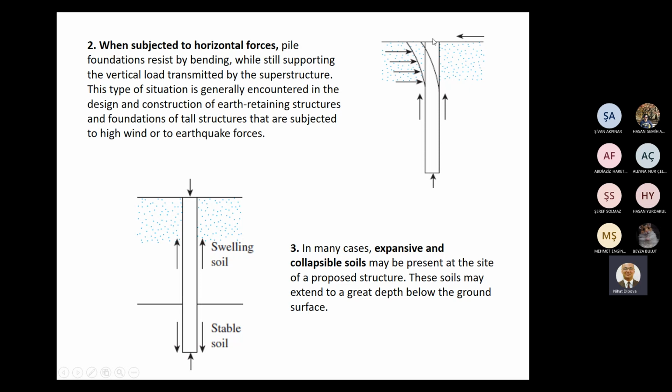We still have structural load, vertical load, but sometimes this pile foundation may be subject to lateral loads. This type of situation is generally encountered in the design and construction of earth-retaining structures and foundations of tall structures that are subjected to high wind or earthquake forces, lateral forces.